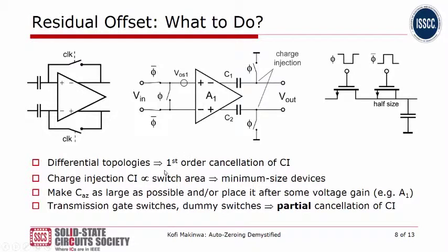Another thing that we should do is to remember that charge injection is proportional to switch area, so we should always try and use minimum size devices. Of course, we also have to be worried about thermal noise and settling time, so this may not always be possible, but this should be the direction in which we're trying to design.